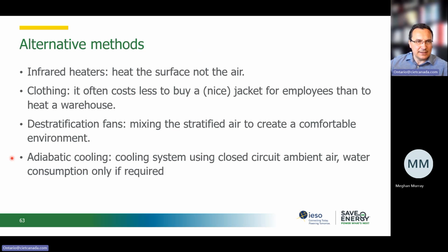Adiabatic cooling, that's another method of improving the efficiency. So basically, we are using a closed ambient circuit for the air, and we use water for the evaporative cooling effect only if required.